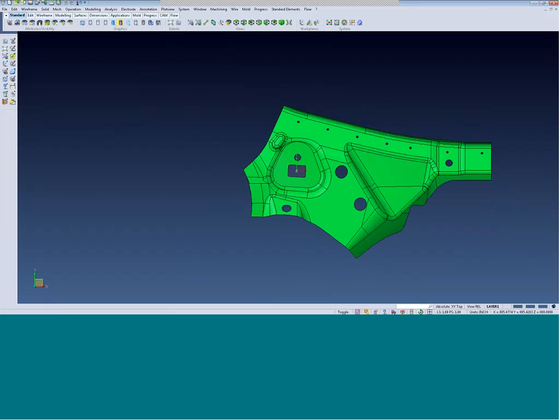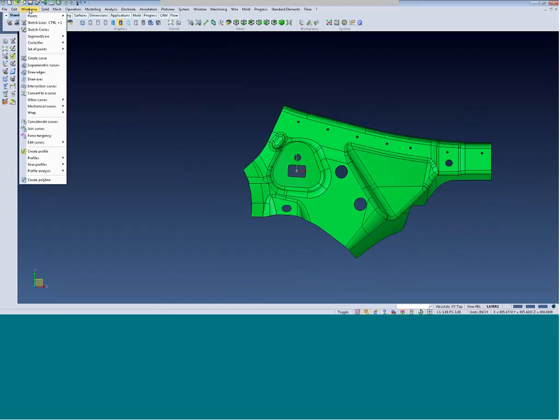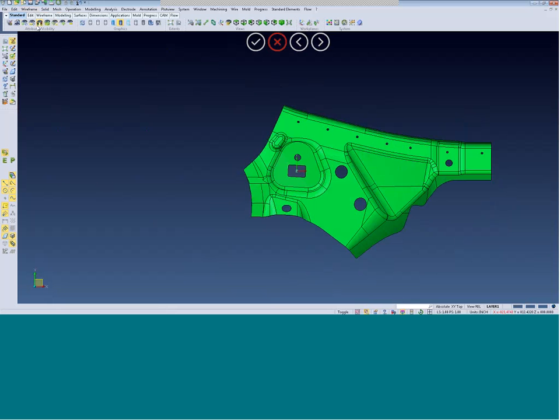And we'll take a look at our sketch lines command, and we'll see the enhancements with that, as well as some of the enhancements with the enhanced pick selection method. Go ahead and go into my points environment, the enhanced pick. And I'll just go ahead and place my first point. And right away, you see, as soon as I place that first point, I have the option to tab through 4 parameters here.